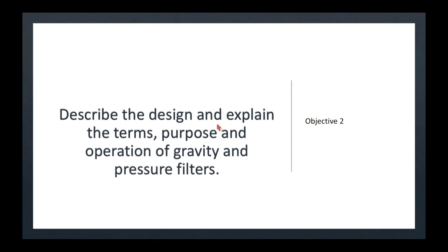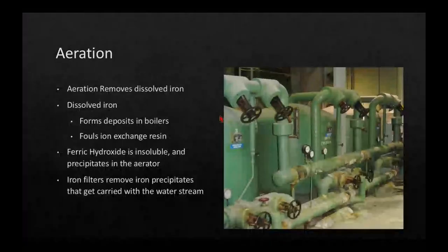Filtration, yes. So then, after we've either clarified or aerated the water, the next thing is we filter it. In the case where we had groundwater that had iron in it, the filtration step is to get rid of any iron flock that may have been carried over.